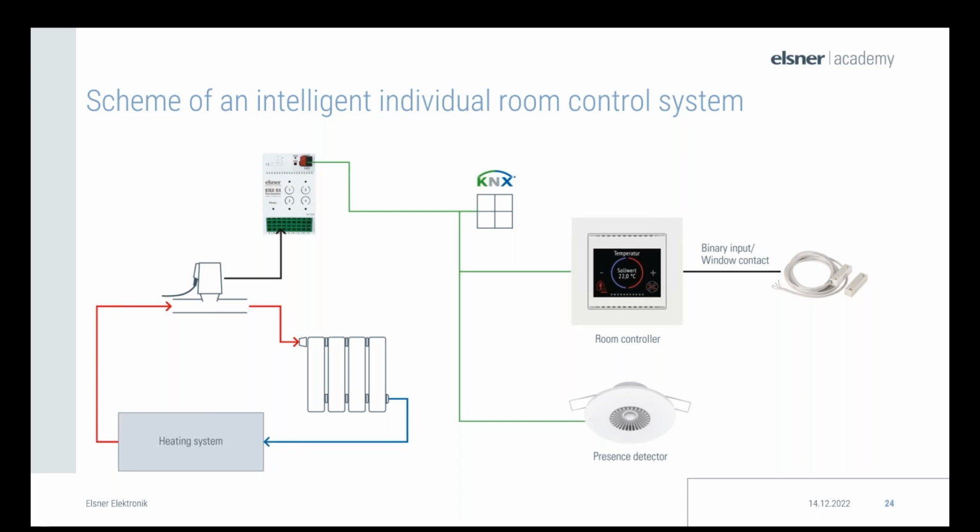So here, for example, the heating could be switched to comfort when presence equals present and lowered to standby when presence equals absent. So this is conceivable, for example, in the use of classrooms or even offices. Once again, a couple seconds to have a look at this slide and time to ask some possible questions.